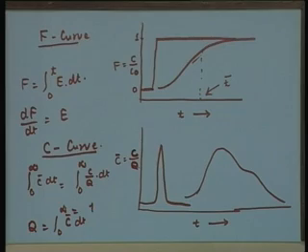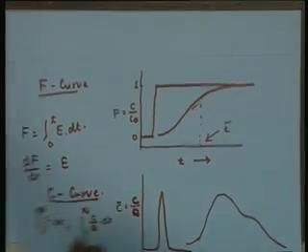Now this tracer information can be used directly or in conjunction with the flow models to predict the performance of real flow reactors. Theoretically, the ideal reactor performances we have been looking at in terms of the reaction kinetics: we develop a mass balance equation for a particular reactor, apply the reaction kinetics, analyze the equation and get the final reactor performance equation in terms of tau versus the fractional conversion or the remaining substrate concentration in the reactor.